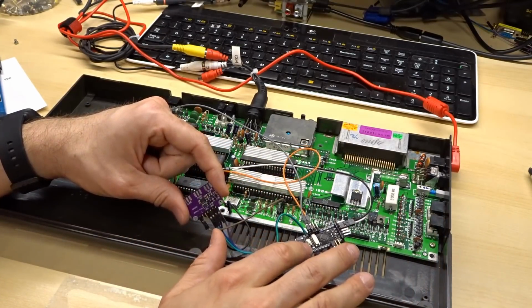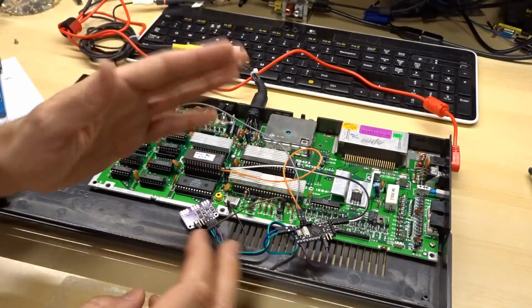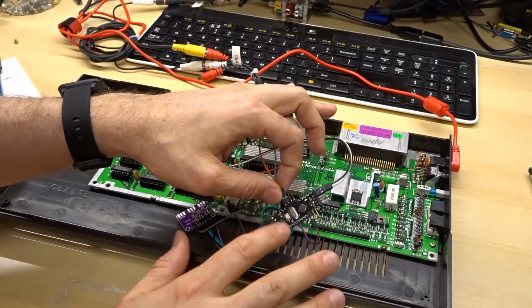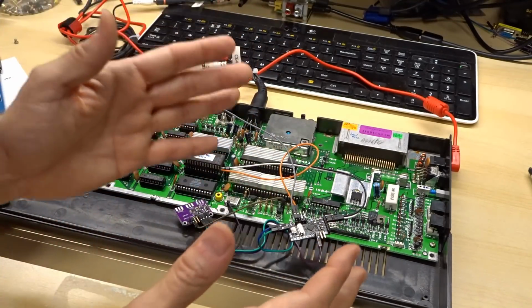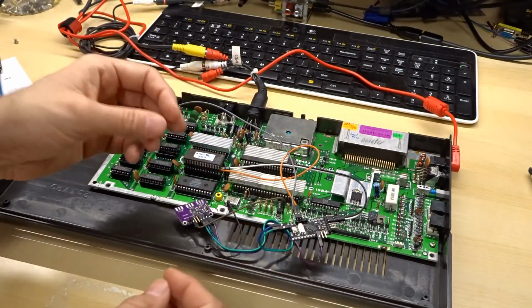So what I did is I've actually reloaded the bootloader onto here, and I use Optiboot. I can't get into how to program one of these in this video. It's way too complicated, but if you look online, you can see how you load Optiboot onto your microcontroller, onto the Arduino. With Optiboot, it essentially starts the microcontroller within a fraction of a second when it gets powered up.